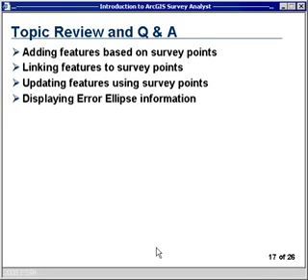Thank you, Christine. If I could just highlight one of the questions that Christine just answered, and that is where Survey Analyst actually works. And she is correct. Survey Analyst actually works in ArcView, ArcEditor, or ArcInfo. Within ArcView, Survey Analyst works on a personal geodatabase. So within ArcView, you can use Microsoft Access to build your survey database. Within ArcEditor or ArcInfo, it can work on a multi-user implementation as well.